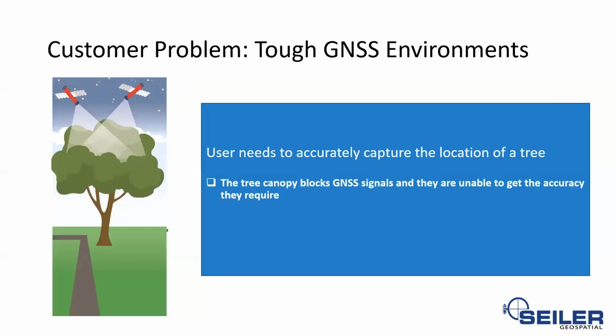So then the other issue that we could have too with GNSS, and if you've taken classes from us or been to some of our workshops, you've heard us talk about urban jungle or urban canyon. When you get into a downtown type setting, you are losing some of your sky view of the satellites, on the angles to the south, to the west, to the east. Same concept if you're in a forest, in a park type setting, or maybe in a canyon or river valley, you lose line of sight. So you're going to have to get yourself in the most optimum area to get good GNSS.